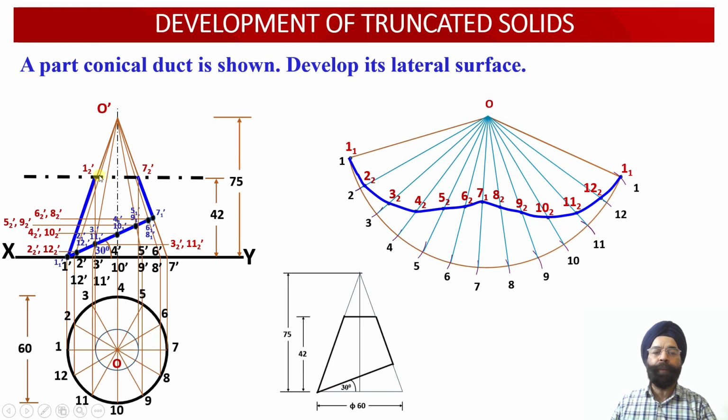So we need not obtain any special or different radii corresponding to the points of intersection of these 10 points. That is why we haven't marked these points in the front view projection over here, because ultimately the same radii we are going to use for all the 12 points corresponding to the frustum of this particular cone.